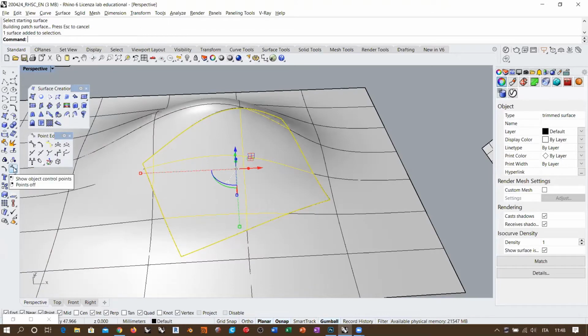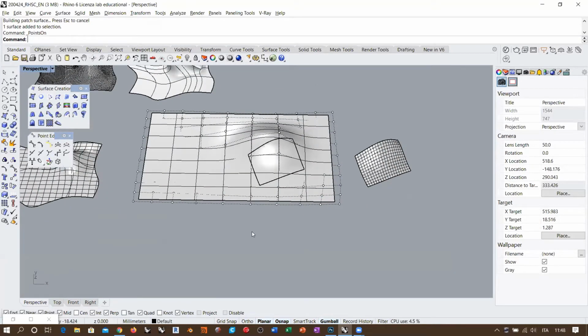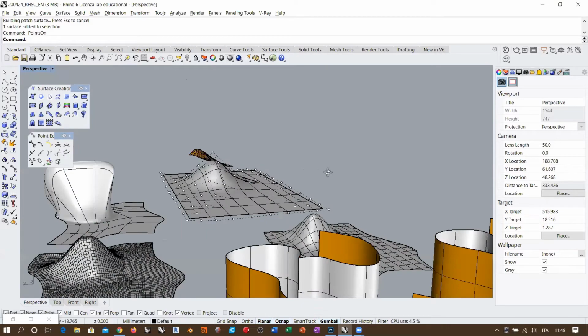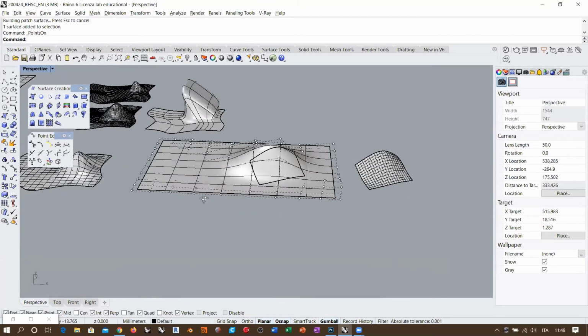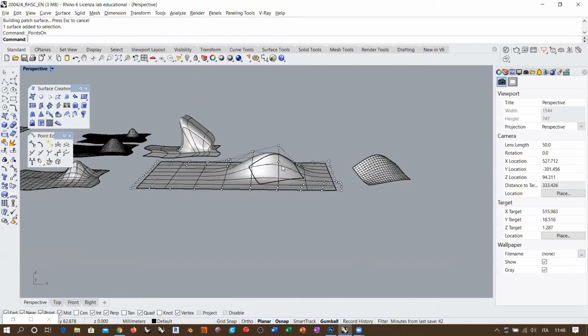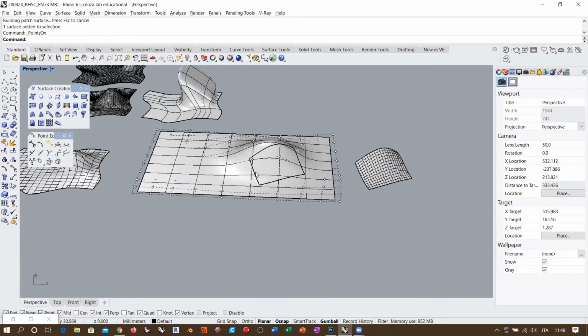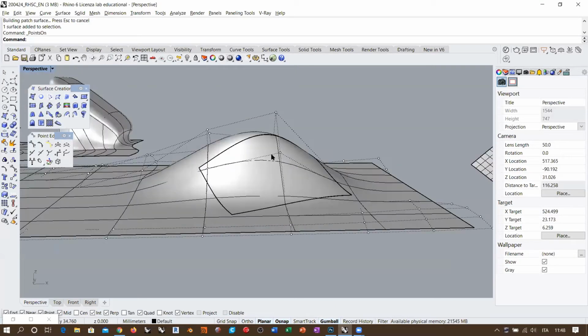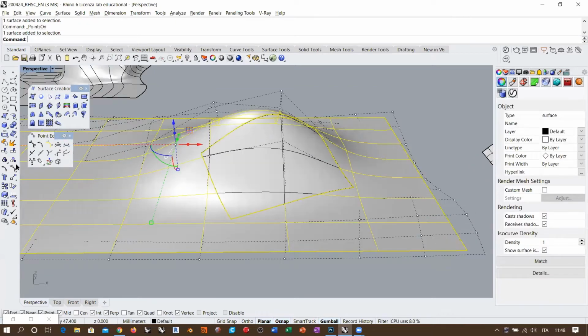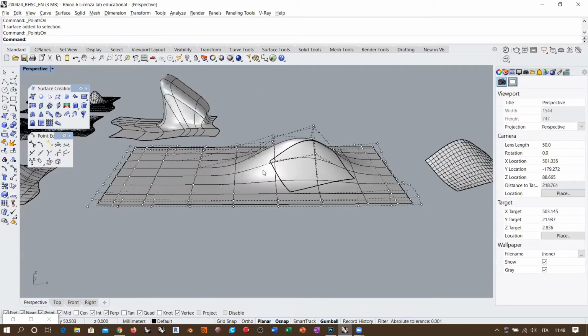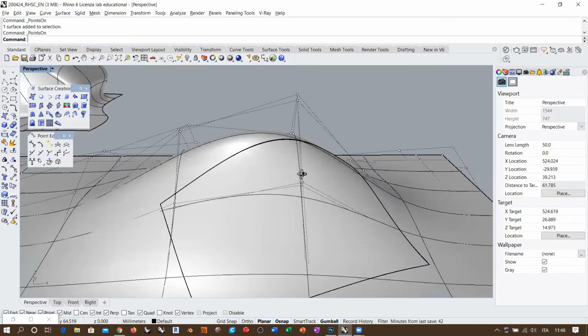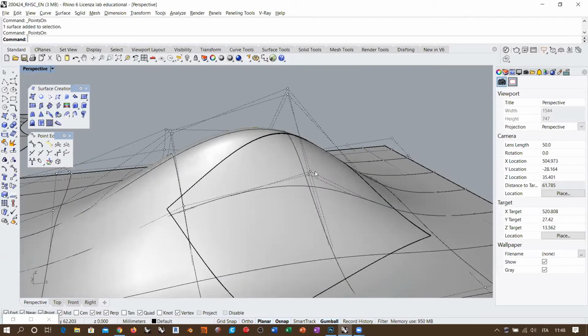And if I activate the control points, look at what we got here. This is exactly, or well, not exactly, but it's the topology of the patch that corresponds exactly to the extension of the surface that we selected as starting surface. So we see that basically, if I select also this one here and activate its control points, you see that there is a whole part of the surface which has the same identical topology, but you also see that there is some deviation between the topology of the actual patch and the original surface. So this patch is not rebuilding the original surface, it's a patch, okay?